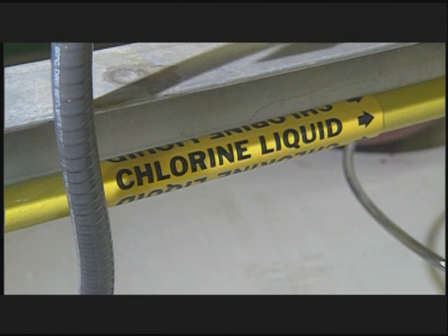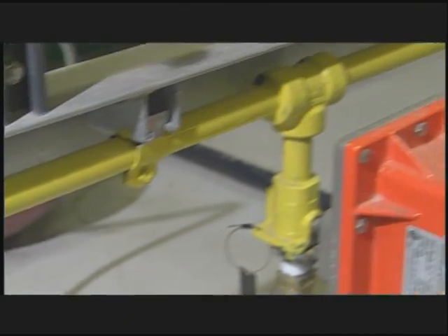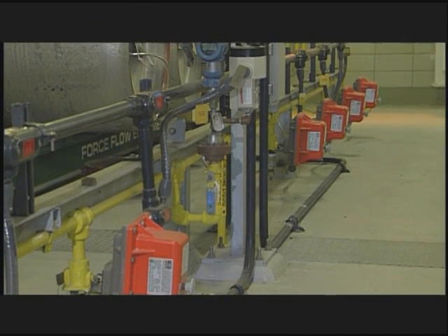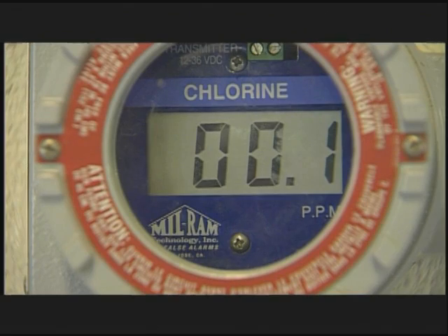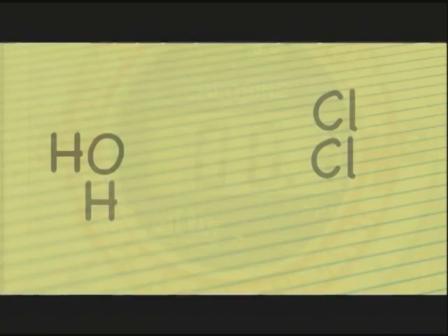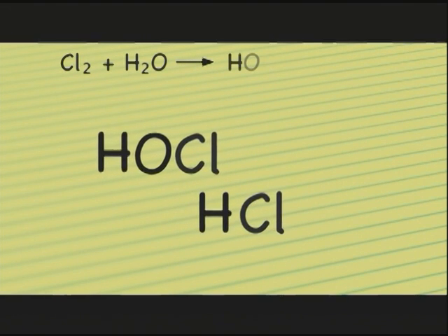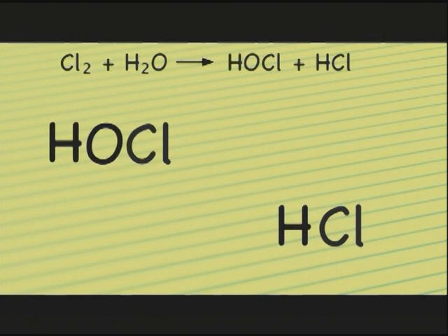When chlorine is added to water, it reacts to produce various compounds. Some are effective disinfectants, whereas others represent the end product of a reaction that has removed an undesirable constituent from the water. In this reaction, the chlorine combines with water to produce hypochlorous acid and hydrochloric acid. Because of the ease with which it penetrates into and kills bacteria, hypochlorous acid is the most effective form of chlorine for disinfection. However, hypochlorous acid is a weak acid, and using what we know about acids, it will further